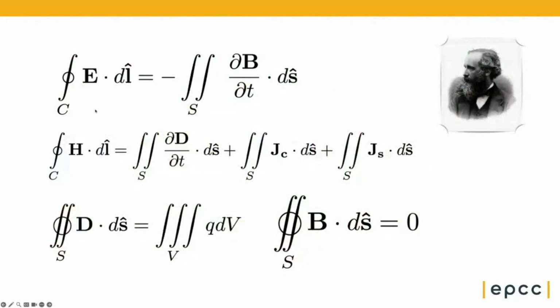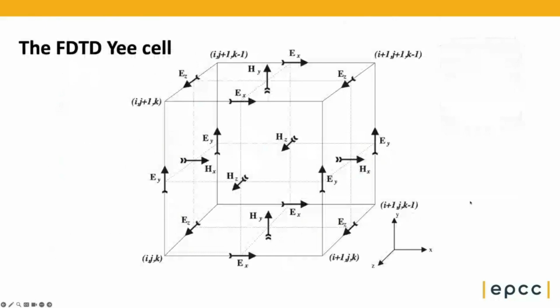How do we do it? We solve Maxwell's equations, which we'll see here. And how do we do that? We use a finite difference time domain technique, which is based on approximating the electromagnetic fields in various components in a rectangular cuboid, most of the time, cell, which we call the Yee cell, from the person that actually invented this technique years ago in 1966.